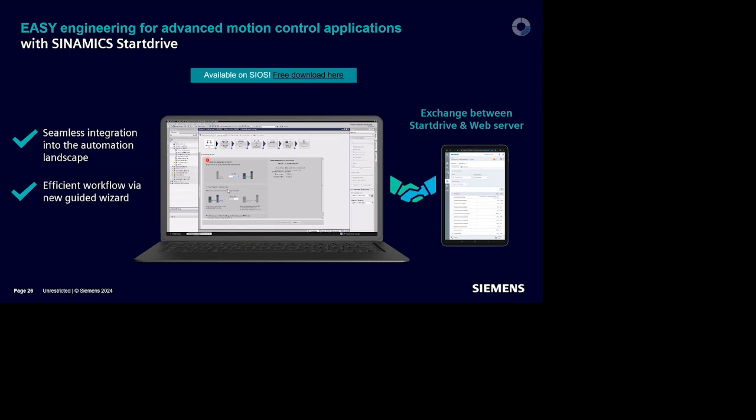Well, this is a thing of the past. This will not happen anymore because every time right before you start a commissioning, the drive will create a backup. So in case of communication loss, the drive will recover this information from the backup, and it will keep running afterwards. So this is one of the improvements.